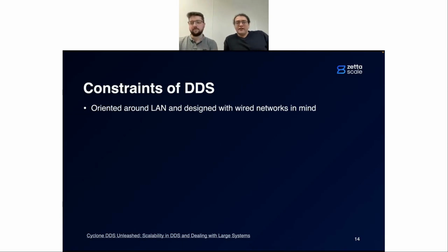Also, it's push-based only, and that just means for certain topologies it's inappropriate to make use of. For example, with the ROS abstraction for actions, you had 6 different topics being communicated against for providing feedback. Maybe it would be nicer to have a single channel there, and I guess on the ROS side that's how it's abstracted. But for some topologies the push-based architecture is just inappropriate.